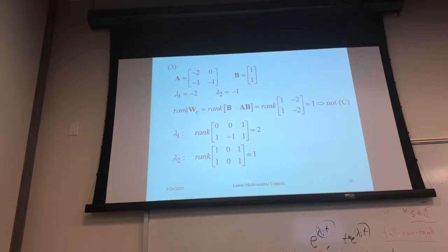Using a simple LTI rank test or using a controllability gradient, you know it's not controllable, but you don't have insights about which mode is not controllable. You don't know that. Then the Hautus test is a simple test that can tell you that. Of course, overall it's not controllable. So this is just a simple example to enhance your concept.